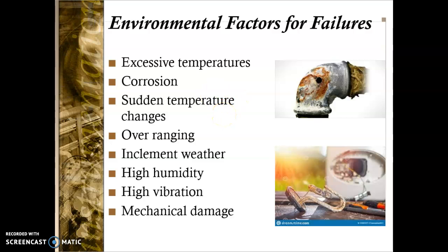And again, we can talk about pressure differences, which could occur if you don't have venting properly and so on. Then you can have corrosion, overranging, inclement weather, and high humidity. These two contribute a lot to corrosion, and making sure that you have the right materials of construction. You could have high vibration and mechanical damage as well.